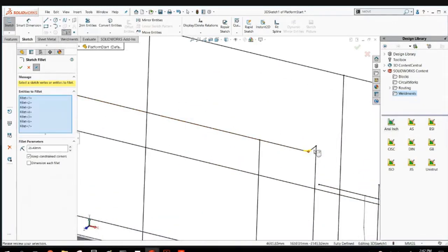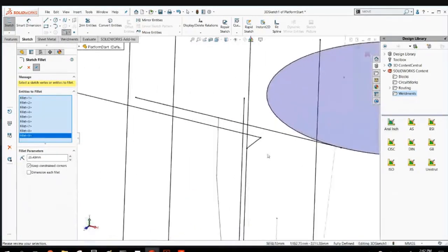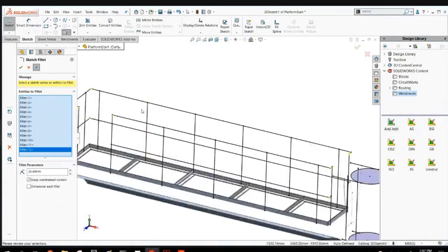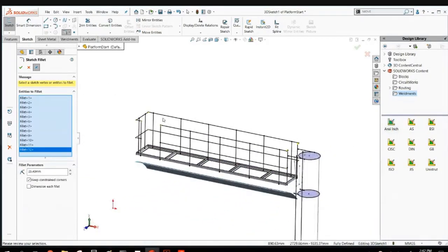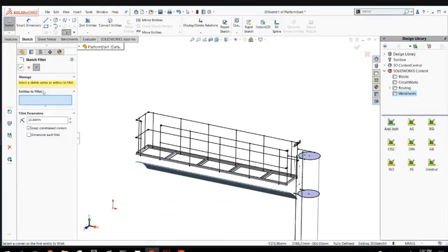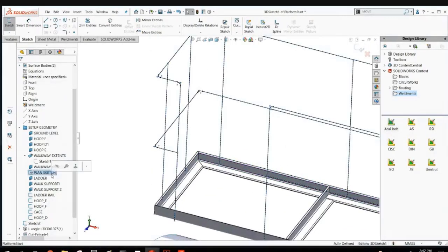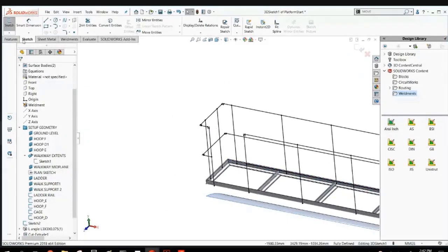Doing this inside of the 3D sketch, you can do it, but a lot of times when you're getting too complex with a 3D sketch, you get things like symmetry happening, and then you try and do this, it'll just make it go bonkers trying to figure out what you're talking about. So a lot of times I just like to create the 3D sketch as an overall view, and then when it comes time to create the individual pieces, instead of using this plan sketch, I'll use this converted one where I was able to round off the corners and things like that.